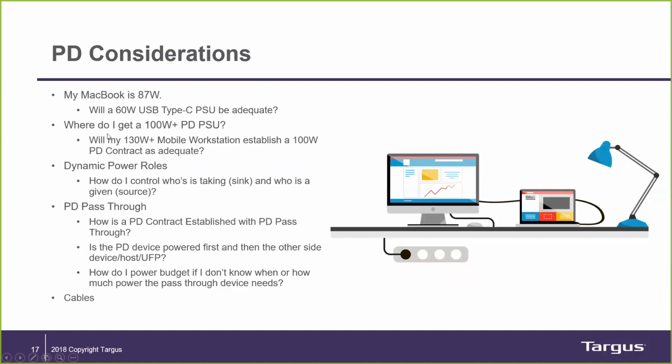Another question I get asked is, hey, I've seen, you said, Kevin, that the specification for power delivery ends at 100 watts, but I've seen devices from manufacturers that have just a single Type-C connection, and they're providing 130 watts or more, and they're allowed to do that.